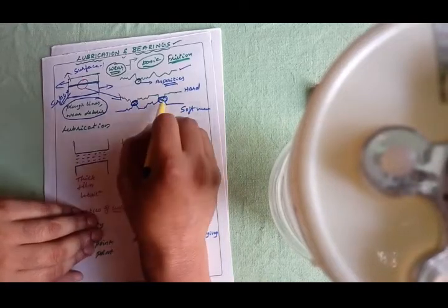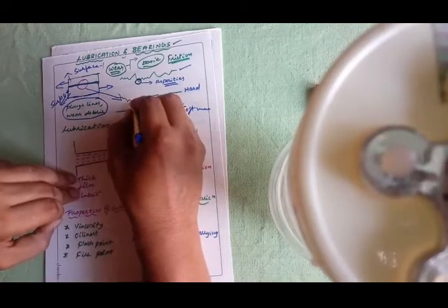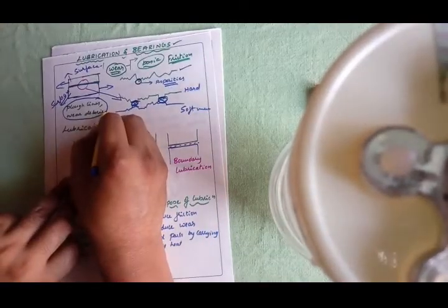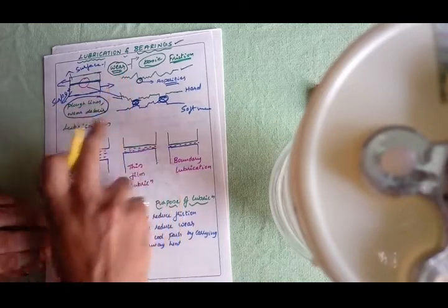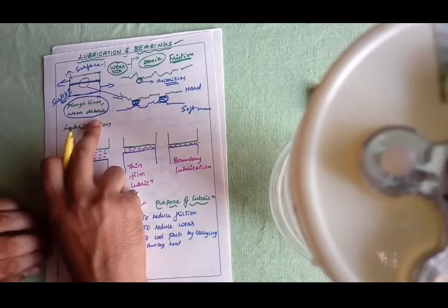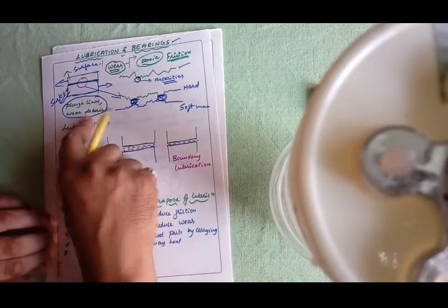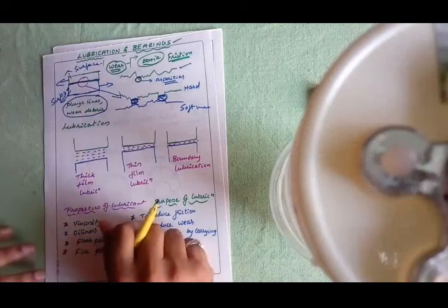When it has been welded and you try to pull them apart, the asperities of the weaker member will be broken out, which may lead to wear debris, which will be in a small powder form. So wear is going to cause flow lines as well as wear debris on your material. Whenever wear debris is present between these two surfaces, it also increases the wear rate.